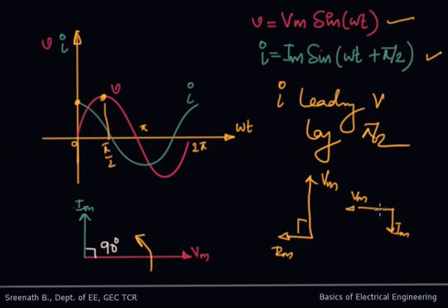Always you will have a phase difference of 90 degrees between those two. So it is rotating in anti-clockwise direction, and that phase difference will be maintained at 90 degrees. And here you have no resistance, you have only capacitance in the circuit. So here in a capacitive circuit, the current leads the voltage by 90 degrees.